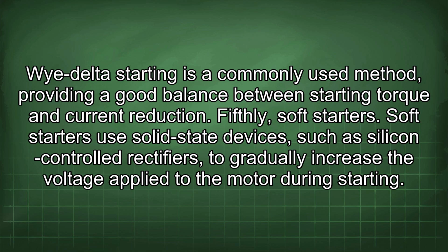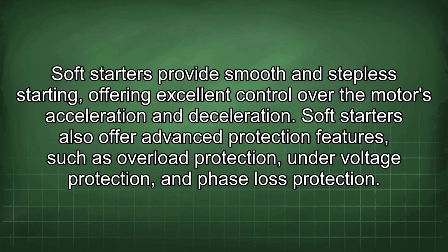Fifthly, soft starters. Soft starters use solid-state devices, such as silicon-controlled rectifiers, to gradually increase the voltage applied to the motor during starting. Soft starters provide smooth and stepless starting, offering excellent control over the motor's acceleration and deceleration. Soft starters also offer advanced protection features, such as overload protection, under-voltage protection, and phase loss protection.